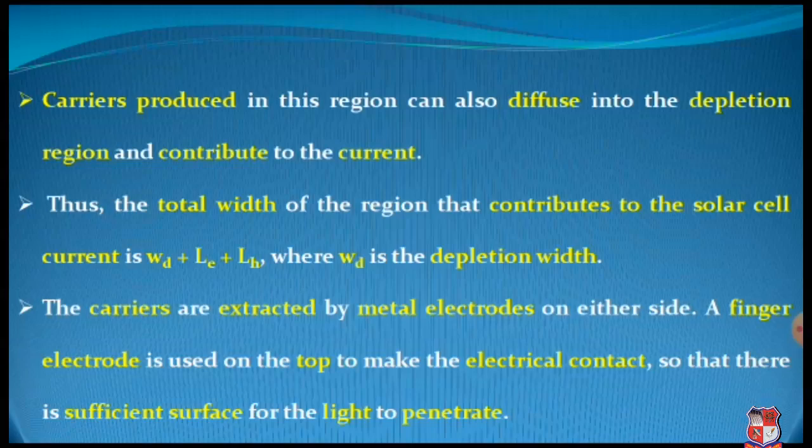So this was all about the principle, that is of photovoltaic effect, its construction of PN junction diode, how these P-type and N-type semiconductors are arranged inside the solar cell construction, and the working in which the main prospect is the recombination of electrons and holes, which majorly contribute to generate electric current inside the PN junction diode, which is further measured by the connected voltmeter.